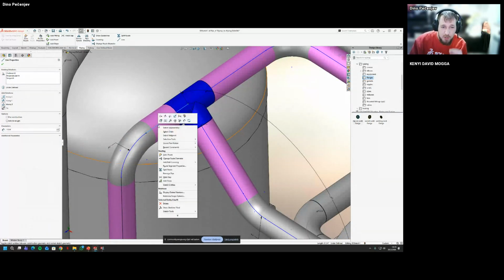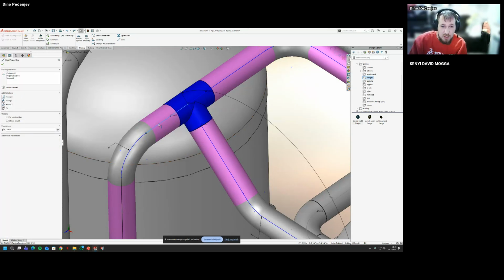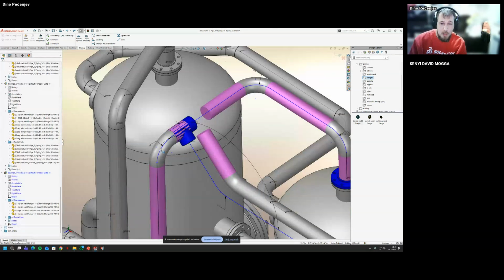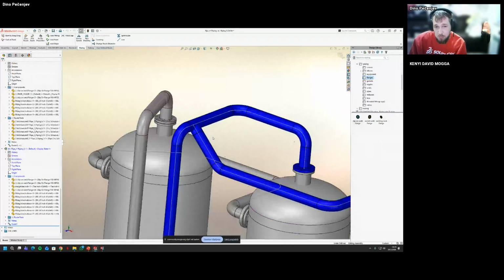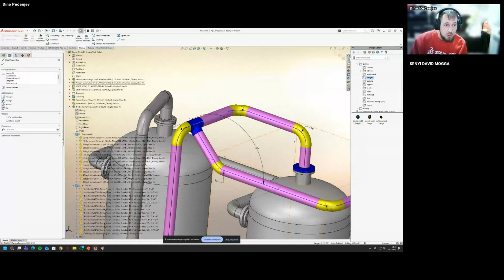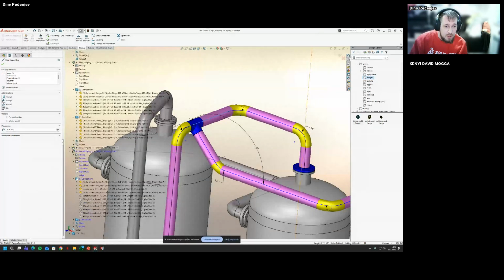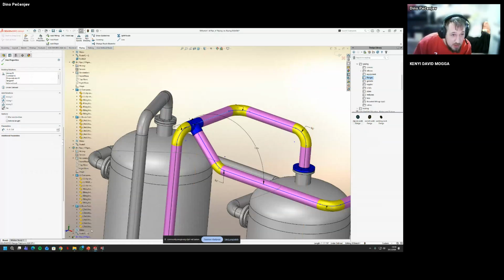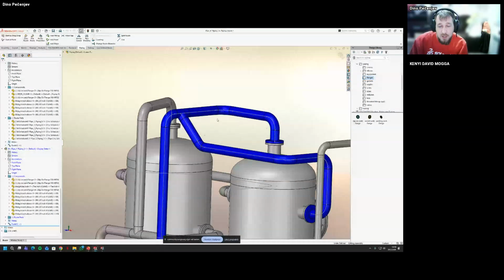So this portion, right click on the part of the routing and remove pipe. Right click, so I'm just going to do Control Z. So right click, we have remove pipe, and it automatically switches the position. And with this, my routing is done. And the last thing I'm going to do, I'm just going to use the plane I created before the previous route. I can use that specific plane, and I'm going to say on plane, so I get the same height propagated here.